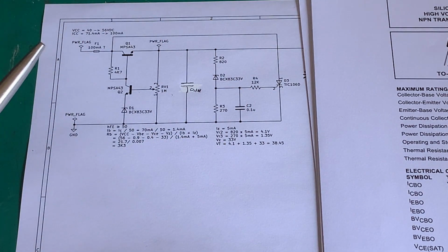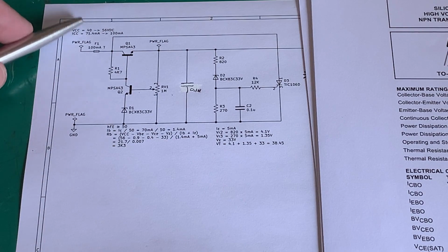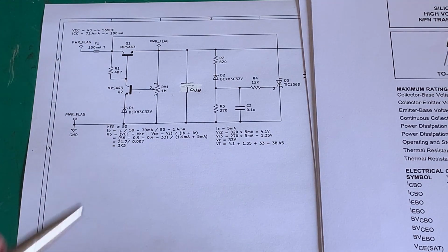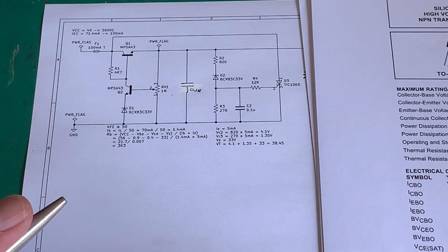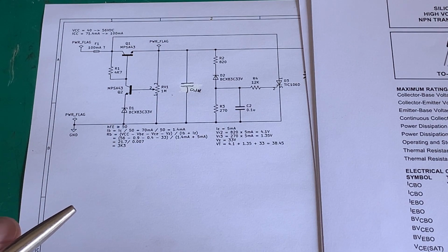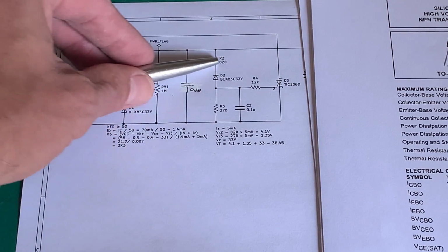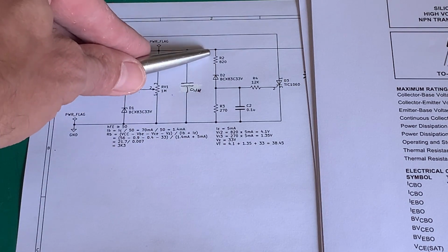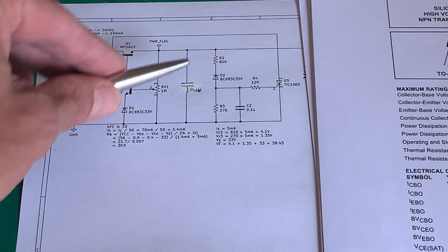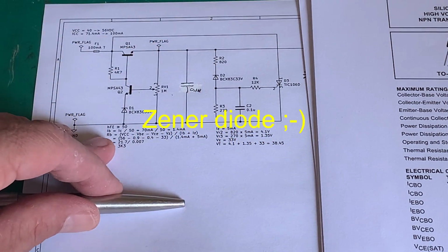So I know from the circuit that we will be designing, we have a voltage input range from 40 to 56 volts, and what I need to power downstream of this circuit has a maximum voltage rating of 40 volts. So I want this circuit to trigger at less than 40 volts, and I can do it by adding these two resistors. So that's a 33 volt Zener, 5 milliamps through the Zener in this case.